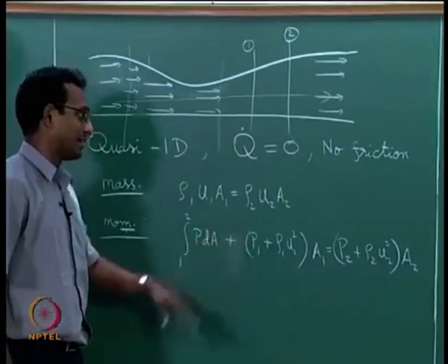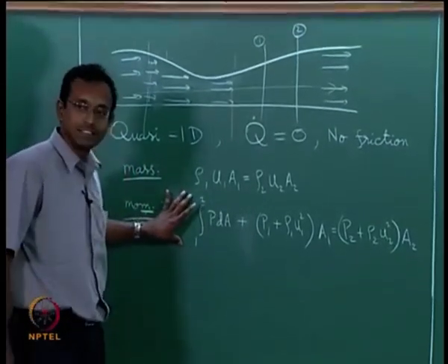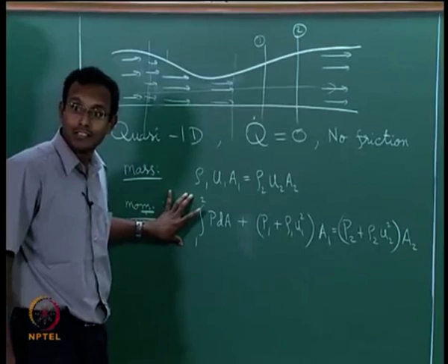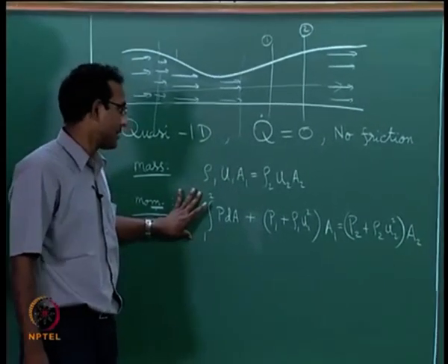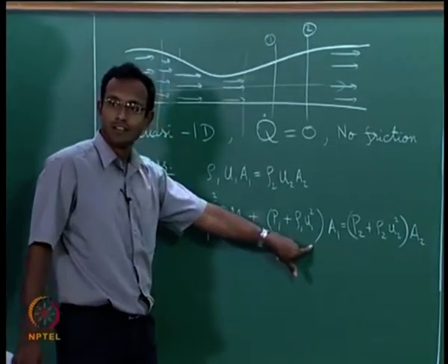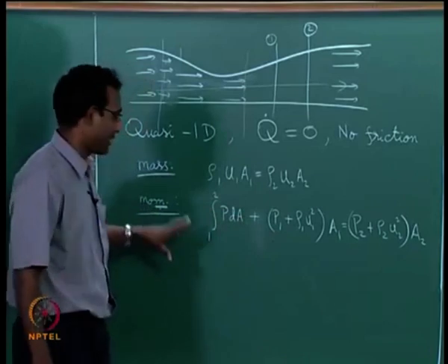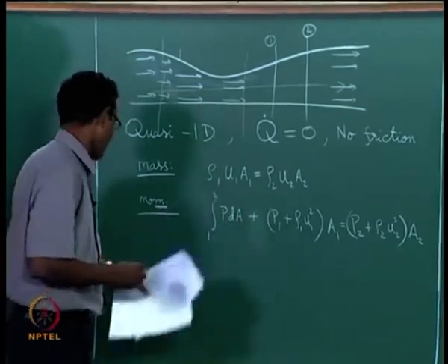It is going to be something like this, and we said that if it is a constant area duct then I can neglect this. Currently I cannot, it is no more a constant area duct, we said its area may be changing. Okay. Initially we said constant area duct, I can say P plus rho u square is a constant, now I cannot do that anymore. I have to be more careful about which momentum equation I am using. This is the correct one to use.